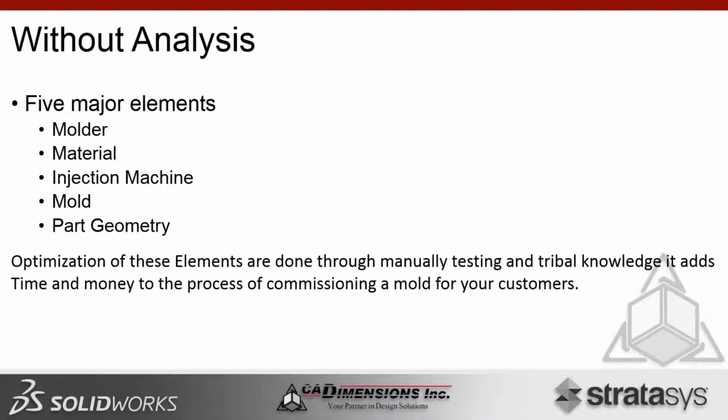But there's definitely a large number of elements that could affect any kind of warpage that you're seeing in a particular part. When you're in this organization, you literally can go and start to look at everything from the material, the injection equipment, the mold, the geometry, and you start to go completely through the cycle to see which elements could be contributing to an issue with warp. And then you're optimizing the elements, maybe through manual testing, maybe you do a DOE and experiment all this stuff out and try to figure out what the contributing factors are.